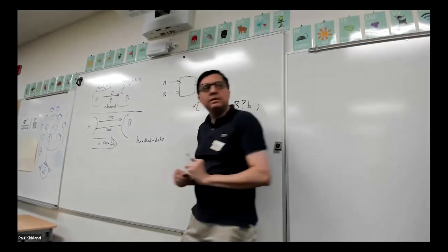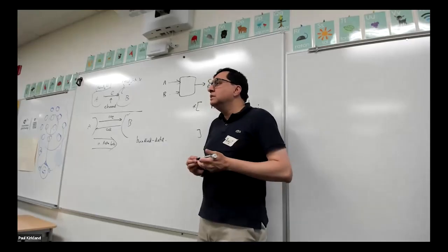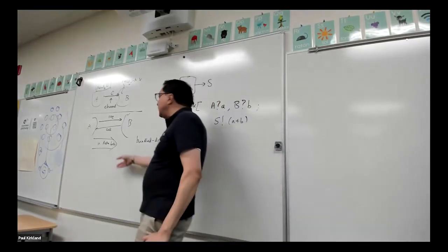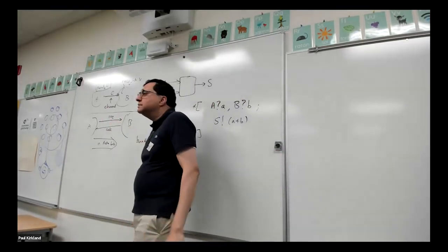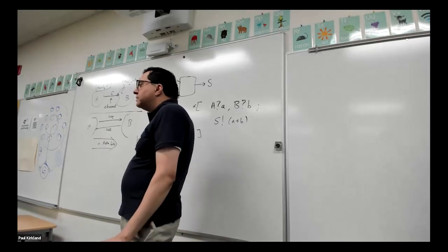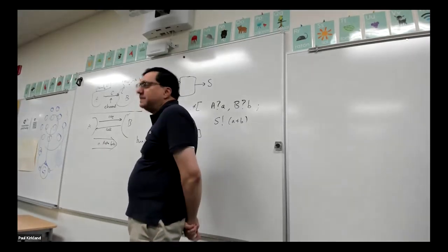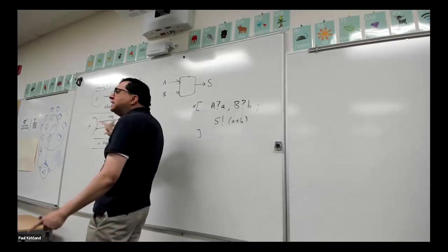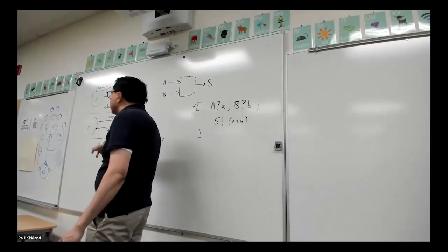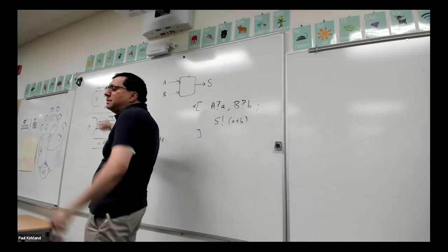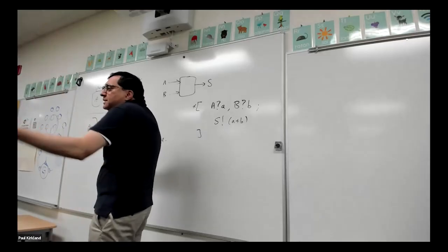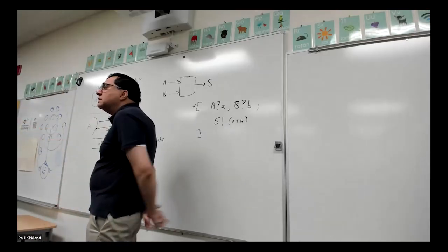So if there's any delay in the channel, then this has to be slower. You add a little gate delay. You have an upper bound of delay. That's right, exactly. All of these are one-sided requirements: this has to be slower than that. The easy way to fix it, which is not necessarily the best way, is to make this slower. So then why is this called delay insensitive?